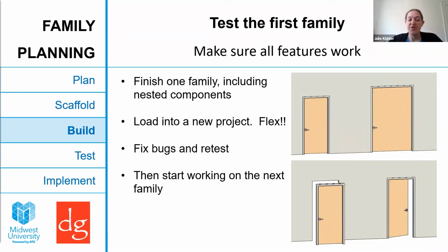Now that you have that first family, test and make sure it works. Change the sizes. Does it offset correctly? Does the door panel open? Keep testing. Each time, think of all the different ways that that family might